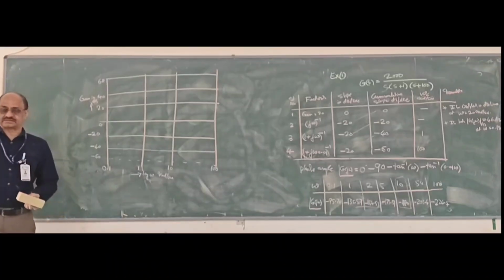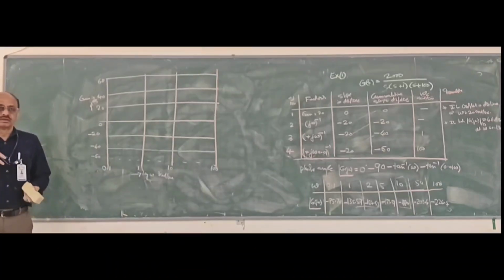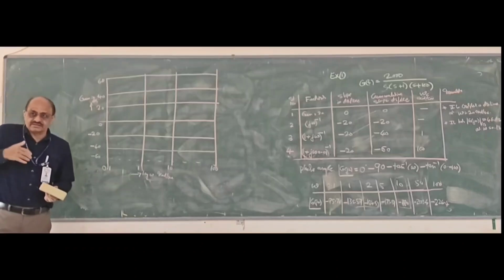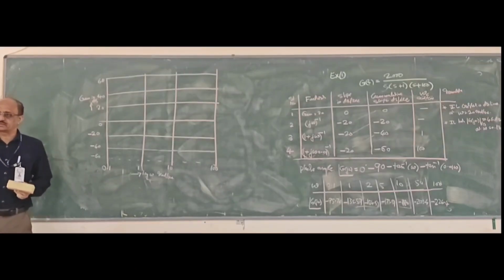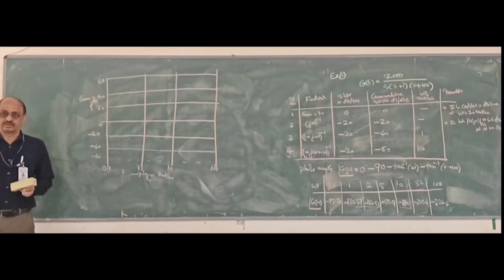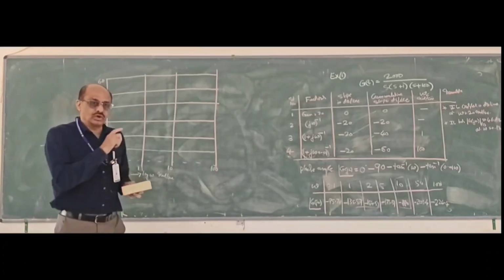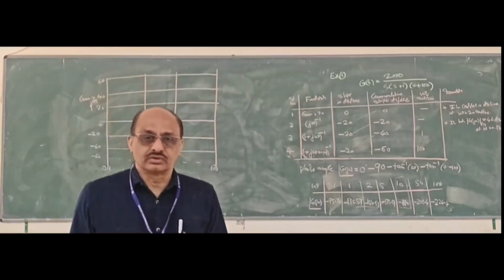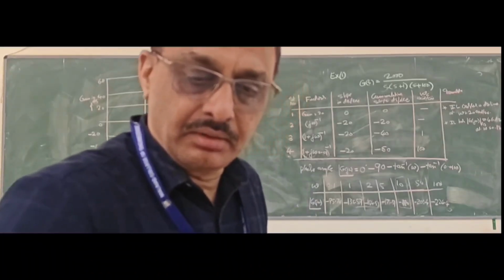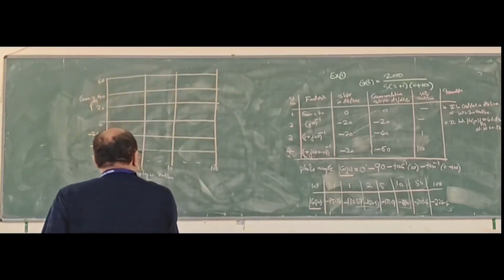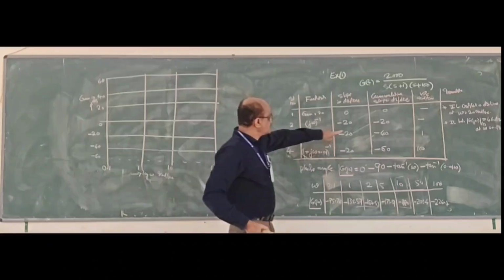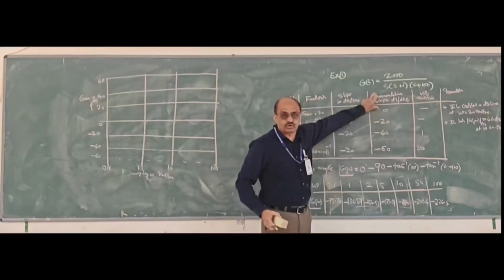All of you first mark these. For our reference, generate the minus 20 dB per decade. I hope you have a ruler or draw scale, so you can draw parallel lines and generate the minus 20 dB line. I need minus 20, minus 40, minus 60, cumulative.